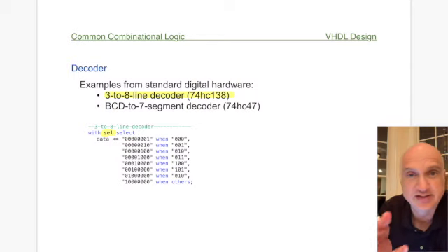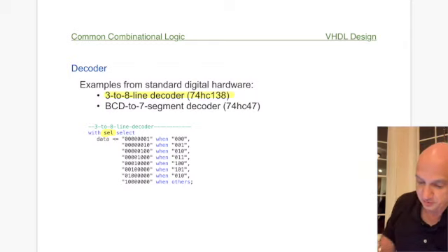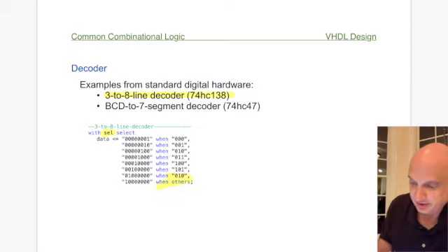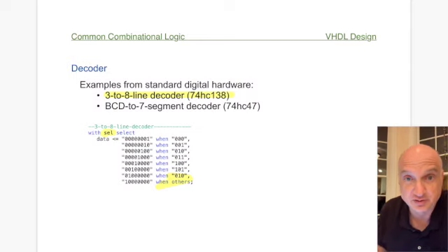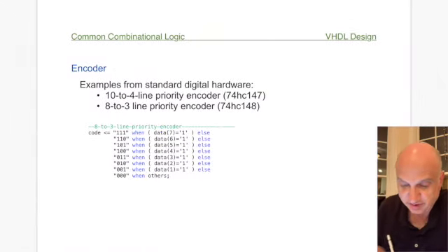So if we're not intending to store information, if we're not intending for a register or a flip-flop to be there to hold stuff, which is sequential logic, then we're obviously going with combinational logic, which is purely gate-based logic, things with and, or, and invert gates, right? And so the others clause is very key to making sure that we generate combinational logic. And so in all of the examples, you'll see the others clause at the very end to ensure that that's the case. So let's take a look at our next example, and let's talk about the idea of an encoder.